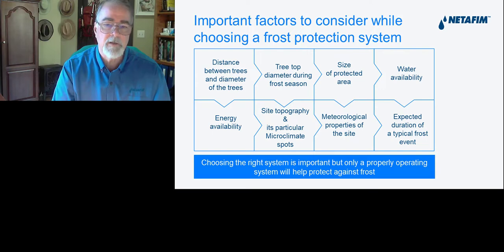In my presentation, I'm going to talk about a minimum of 37. And the reason we talk about those temperatures is because there will be a temperature drop when that water first starts going into the air. So we might be at 40, but if you've got a good temperature sensing device and you first turn on those sprinklers, you're going to see that temperature drop 4, 6, 8 degrees.